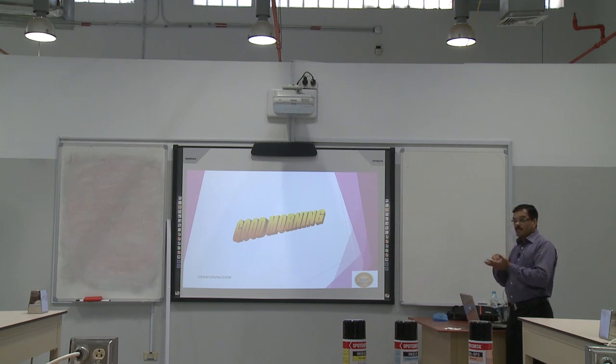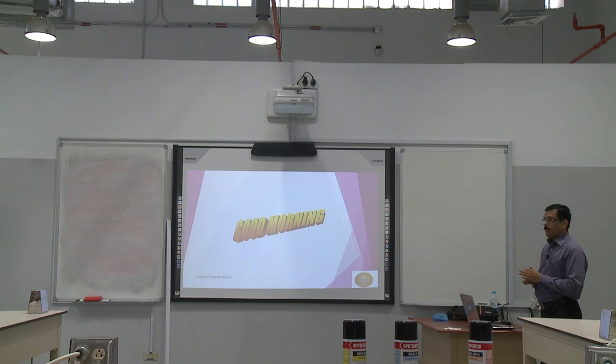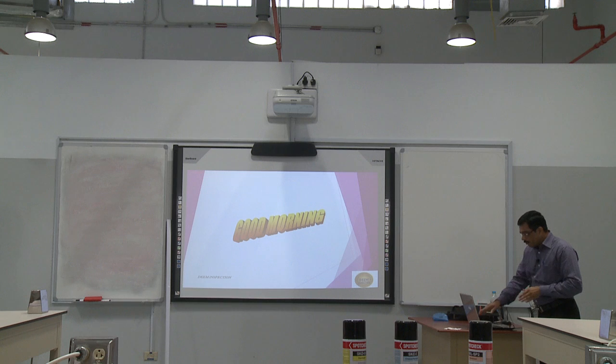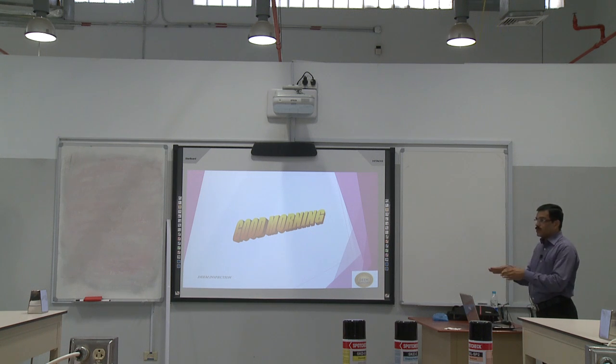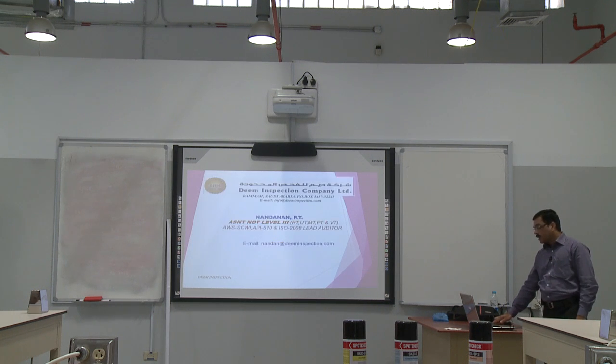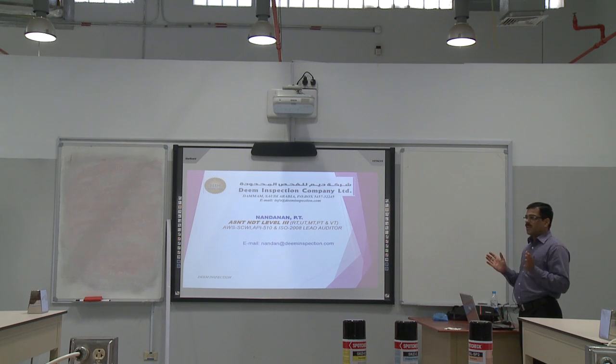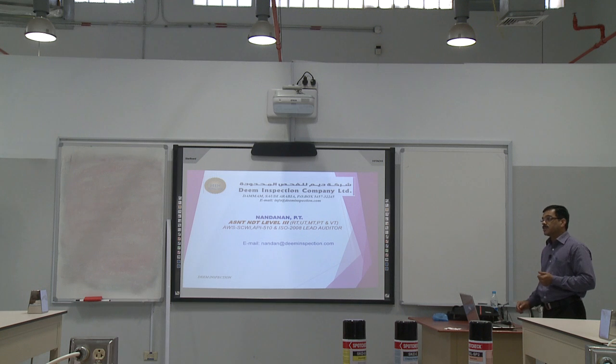So, penetrant testing is a method to detect surface discontinuities which are open to the surface. Such defects we can find with penetrant testing. So always, if there are any cracks or similar defects, they should be open to the surface. That is the method we use for liquid penetrant testing, and it is very economical, very easy, not a too critical procedure, and not too much skill is required. It is one of the economical methods we use to find surface discontinuities.